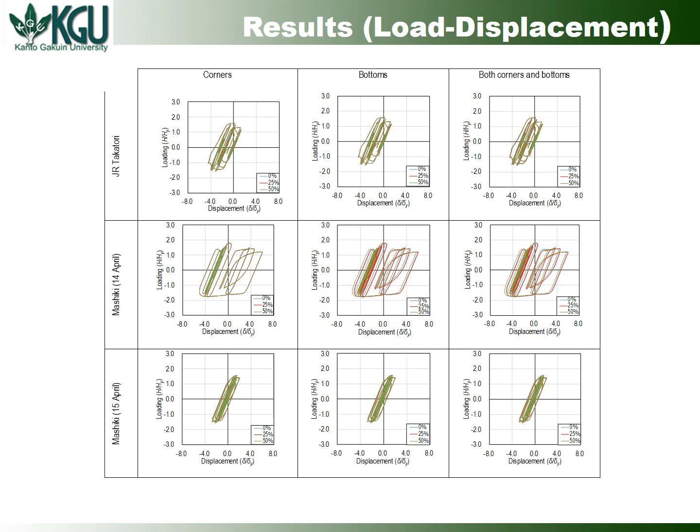The elastoplastic behaviors of the analytical models are almost similar. Moreover, the overall load displacement relationships don't significantly change irrespective of the corrosion damage ratio for all of the corrosion damage cases.